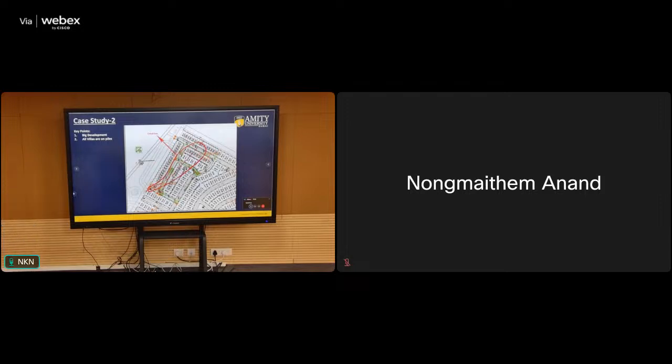Understand? So the project starts. When this entire area was developed, the construction waste was not compacted properly, and what happened? It is very loose. Again, the same problem. Beside this, a contractor was constructing a pipeline and did dewatering, and the loose material inside it subsided. So here also, one of the issues is that no site history was available for the people doing this project.